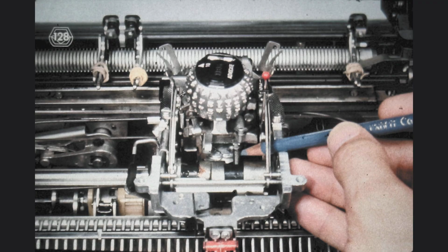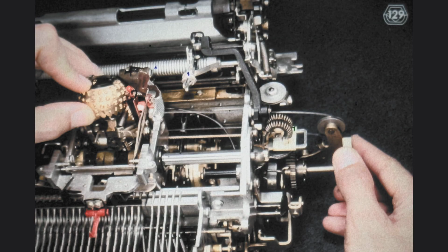Now we need to position the rotate tape properly around the pulley, around the guide shoe we studied earlier, and around the pulleys on the shift arm and the rotate arm, so that we can release the engagement of the rotate detent. While you align the tape around the rotate pulley and the guide shoe on the rocker, use a small screwdriver held over the T-shaped end so it does not lose its position while you work the tape around the pulley. Once you have guided the tape properly around the rotate pulley, there is no need to hold it in place any longer. At this point, we are ready to release the rotate spring tension.